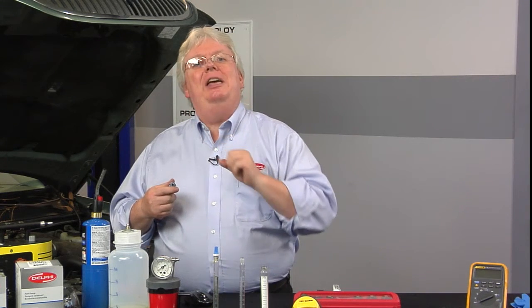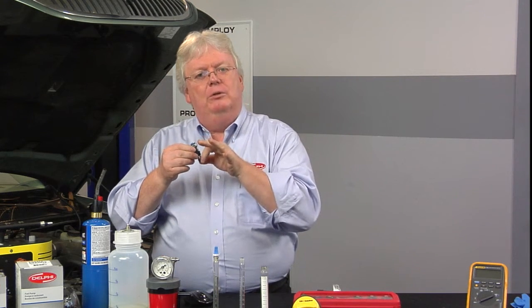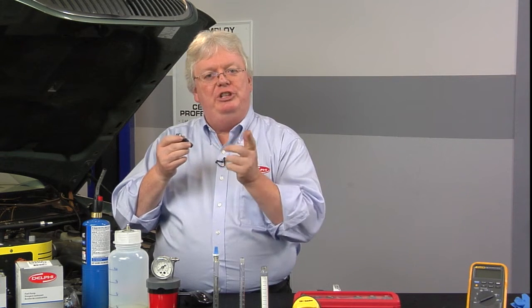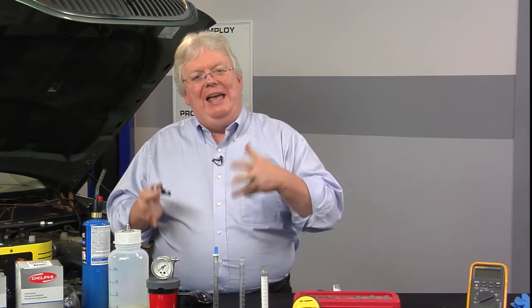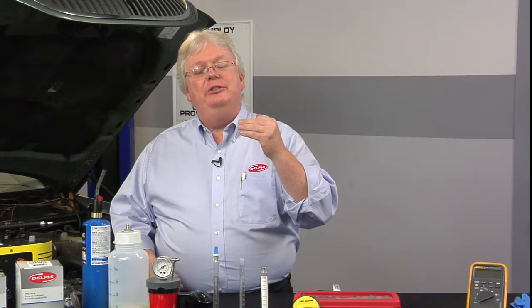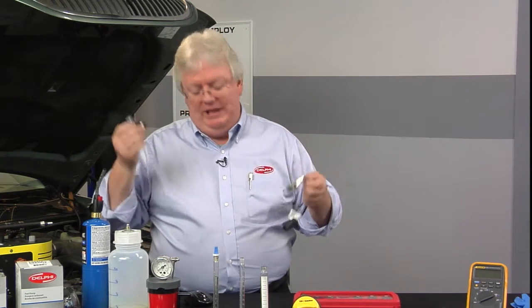One drove the fuel trim up a little bit, the ignition-related misfire. The other, a bad injector not spraying fuel, a fuel-related misfire, drove the trim up profoundly. What was the difference? The way combustion reacts. So just remember, trim increases from ignition misfires are less profound than trim increases from a true air-fuel ratio problem like a bad injector type of misfire.